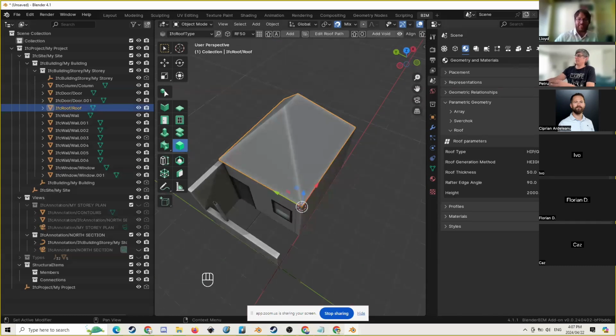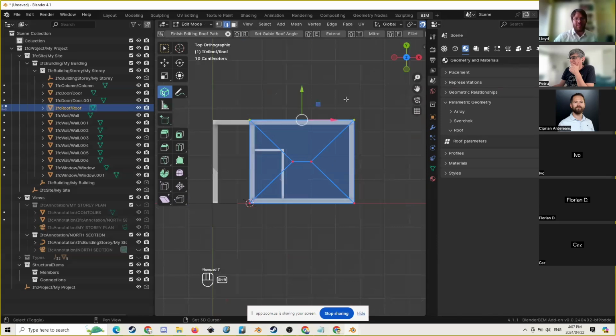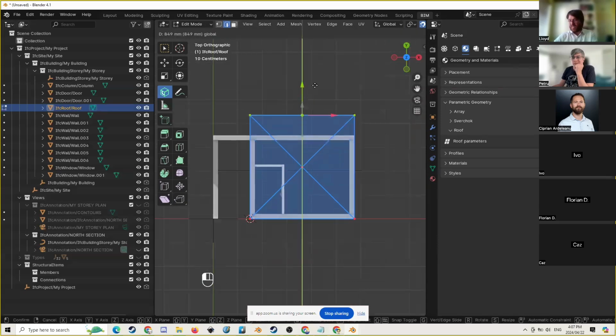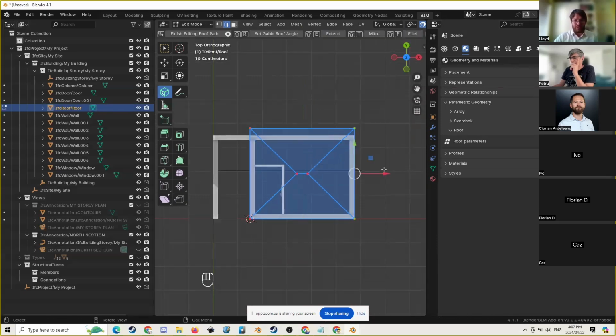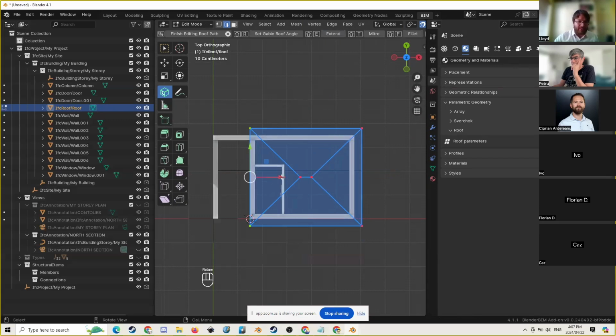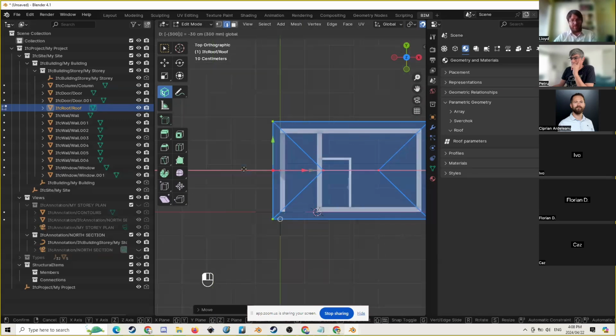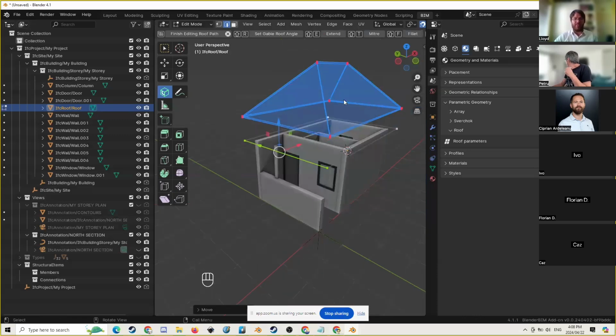We have to finish editing this. I'm going to press Tab again. I'm going to go to my plan view, and I'm just going to offset this by 300 in all the directions. 300, minus 300. And maybe we want it to overhang this whole thing here. Minus 300. So there's our preview tab.